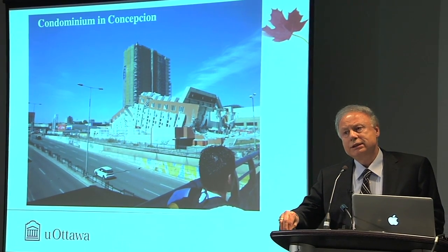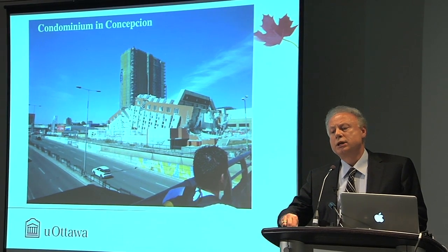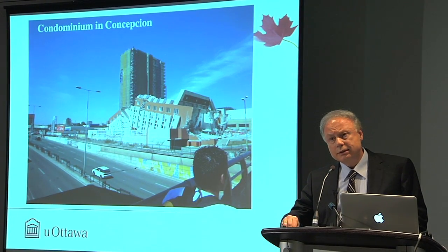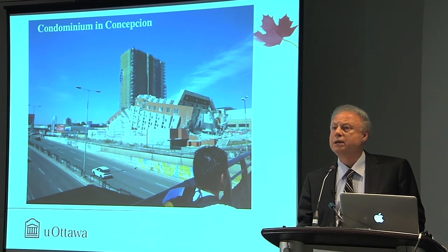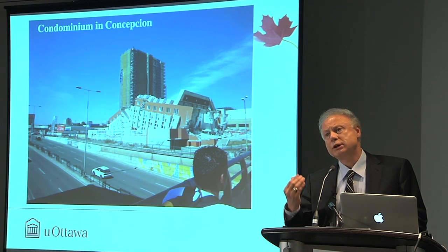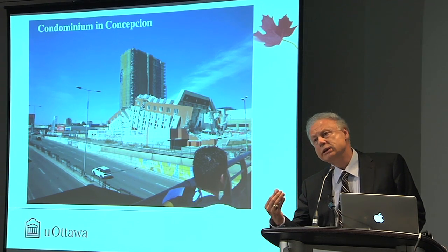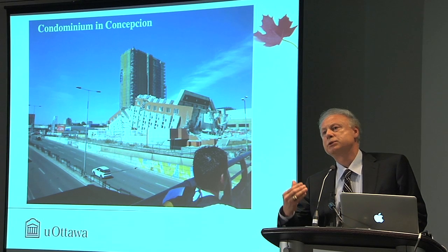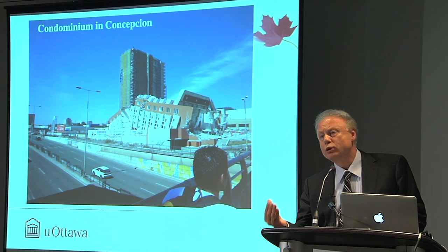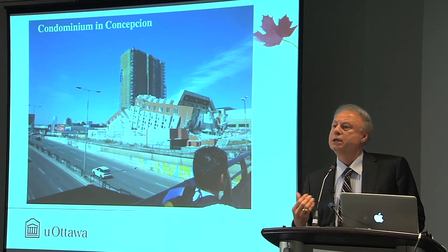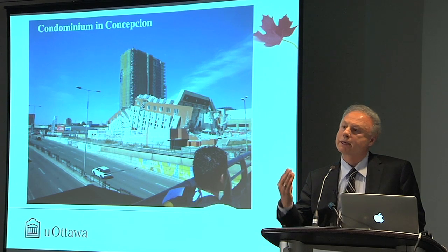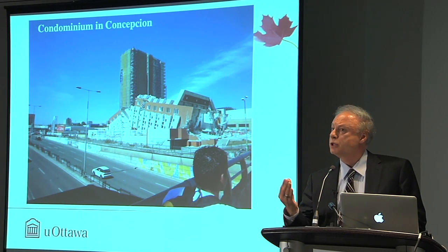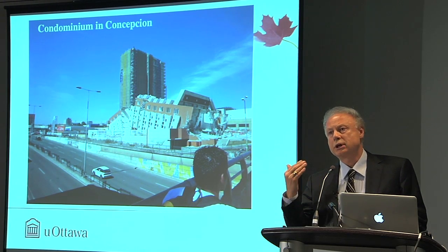Now, factor C, I said, introduces design and detailing practices employed by various building codes. And if you have sufficient strength and ductility, then the buildings would attract a certain amount of seismic force, and then they would yield, and they would become softer, their period will elongate, they will no longer attract as much force, and they will dissipate energy, bounce back, and survive the earthquake. But if they don't have that, then obviously they will fail.